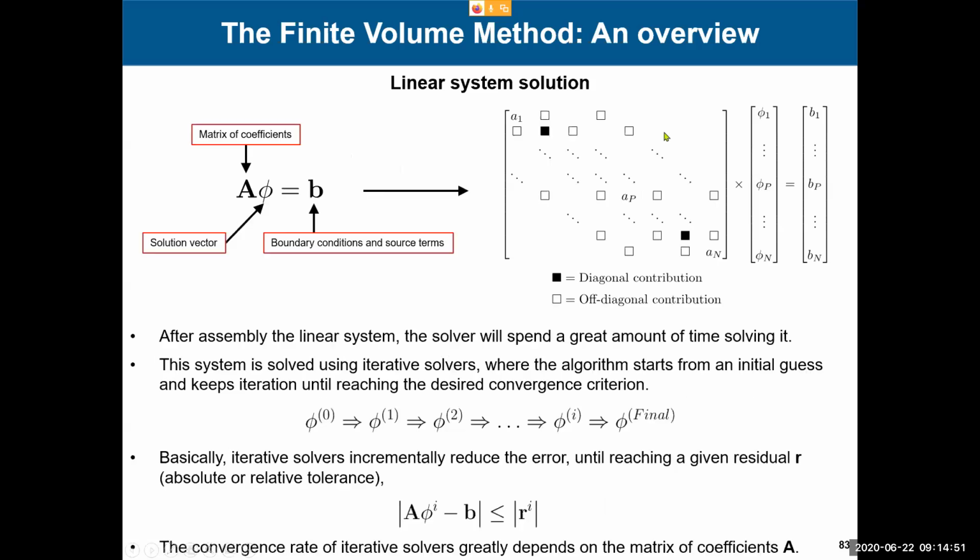You assemble everything, so now you can iterate. So you start from an initial condition, okay? Your folder 0, you iterate, reach your final tolerance, and then you move to the next iteration. It can be iterative steady solvers, or time-stepping unsteady solvers. And this is how you proceed.